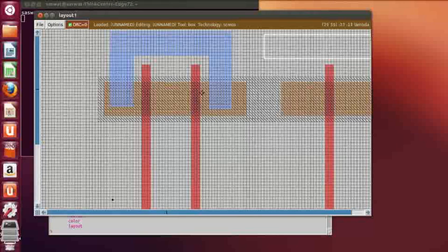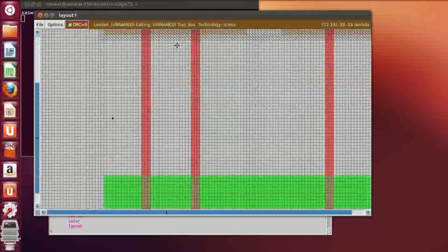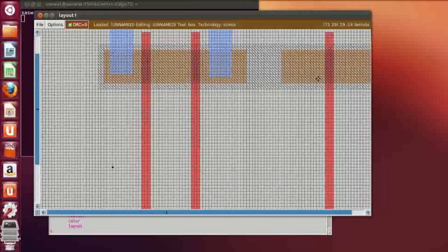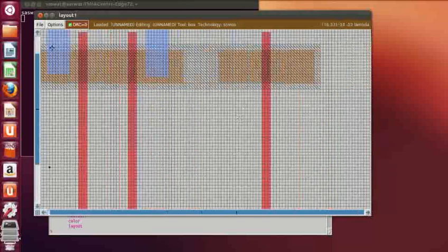So this is A dot B, the two PMOS in series, and this is the plus C part, that is the third input is in parallel.